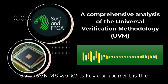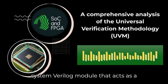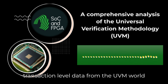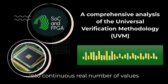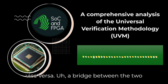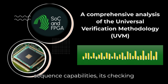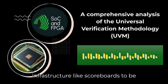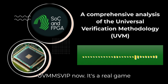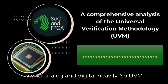How does UVM-MS work? Its key component is the MS bridge. It's essentially a special SystemVerilog module that acts as a translator. It converts digital transaction-level data from the UVM world into continuous real number values that the analog simulator understands, and vice versa. Ah, a bridge between the two domains. Exactly. This allows UVM's powerful stimulus generation, its sequence capabilities, its checking infrastructure like scoreboards, to be applied effectively to analog behaviors too. You can have reusable UVM-MS VIP now. It's a real game changer for verifying modern SoCs that blend analog and digital heavily.